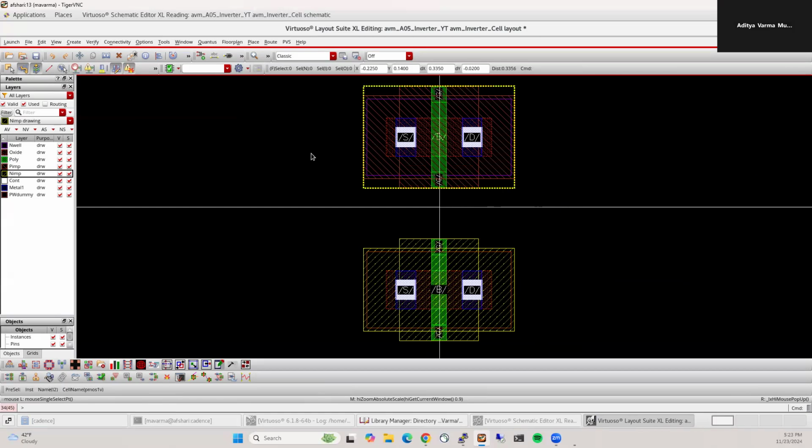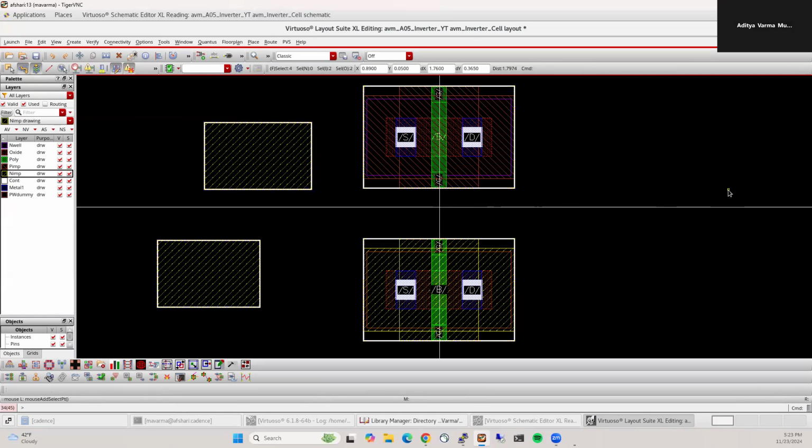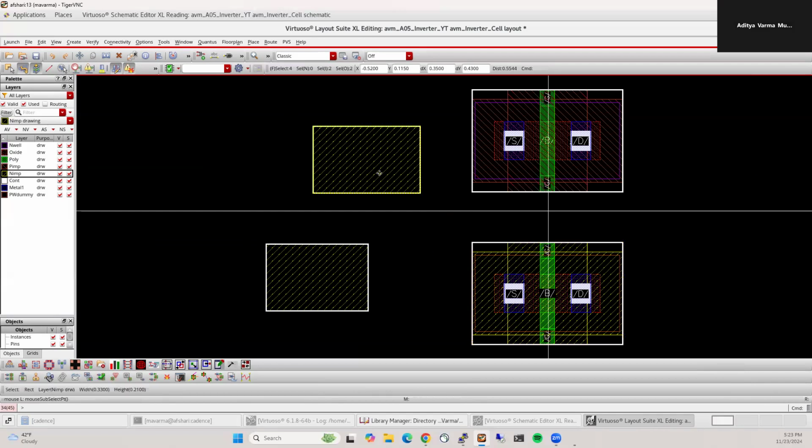And of course, if you want to select multiple objects, so let's say I make many rectangles, I can click Shift and then select all of them. If I want to deselect one of them, I can click Control and then deselect. So for example, if I select all of these guys and I want to deselect one of them, I can click Control and then click on that.